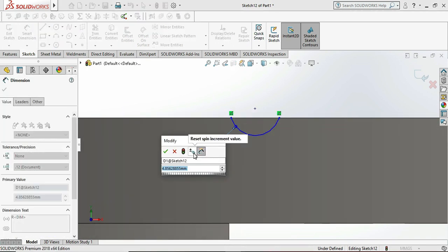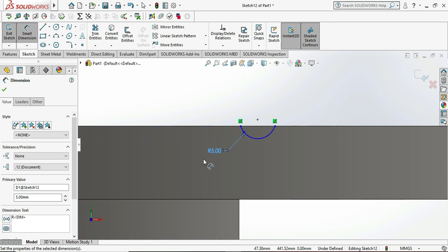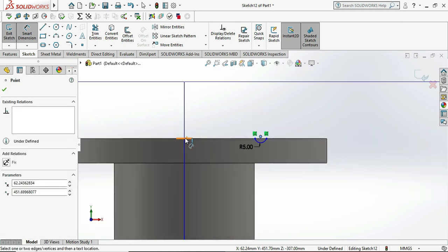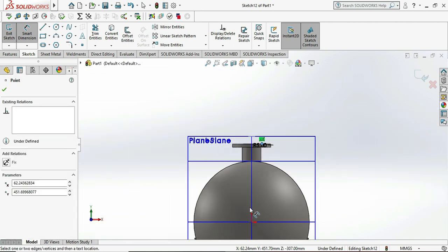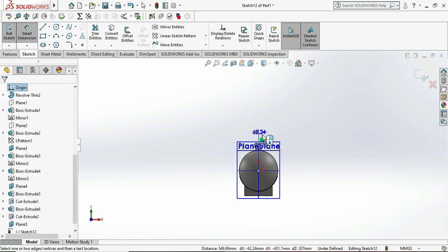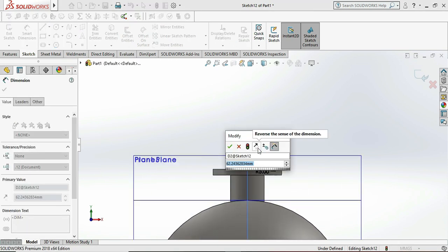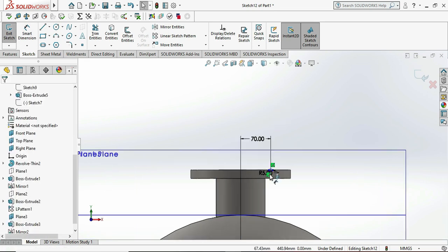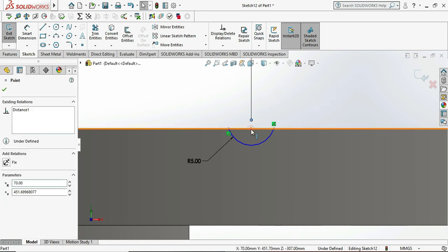This is usually used for the fitment purpose. The ceramic rope does not allow the gas to pass from the flange, which makes a bonding between the upper and bottom flange. So we are choosing the R5 flange or the U groove here.